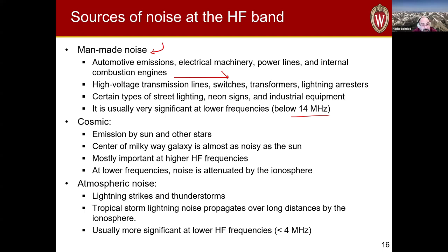There's also cosmic noise, so emission by the sun and the stars in the center of the Milky Way, and all of these also contribute to noise at the HF frequency band. Although these become a little bit more significant at higher frequencies than the HF, because again, that ionosphere, when it's blocking signals radiated from Earth from going into space, it also does the same thing for signals or noise that's coming from outer space, into the space.